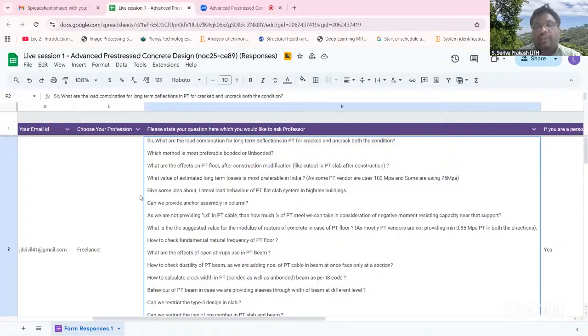Yeah. So depending upon the thickness of the slab and the span of the slab and your elastic modulus, there are some empirical equations that are available to calculate. Otherwise, what we do, if you're not concerned, is a drop weight method. You drop a weight and put some sensors to measure the vibration. Then you can also assess. So those are the ways that we typically assess. Or we do the finite element analysis to find out what is the natural frequency of the slab.